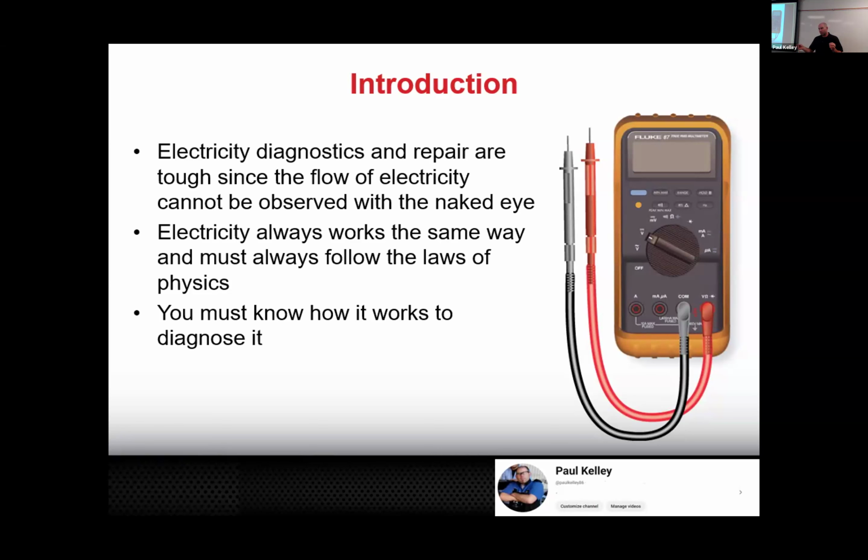To really verify what it is 100%, now you've got to try to drive it and goof around with it again to get it to go out. So what we like to really do is just leave it undisturbed and take measurements. If you had, for example, high resistance in a connector and it wiggles just the right way, and boom, the light bulb goes out, and then you wiggle it, and the light bulb comes back on, you can probably generally tell it's going to be in that connector.